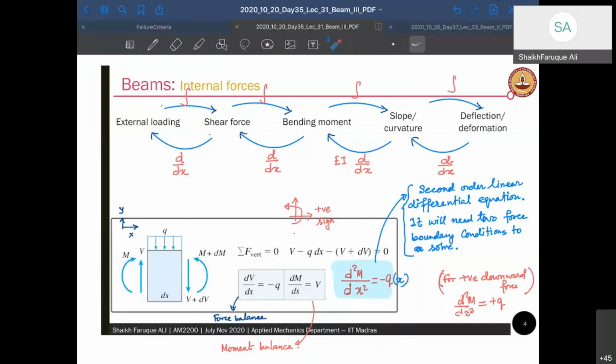As long as we assume very small deflections, very small strains and stresses, we are going to work within the first order derivative terms, not in the second order derivative terms. Second order derivative terms will lead to square terms, which will lead to nonlinear stress deformation relationships and nonlinear geometric deformations of the beam, which we disregard for your undergraduate courses itself. That's a good question, Abhishek. That's a good point that you have put up. Yes, there will be a second order term, and you have to avoid it. So neglect the second order term.